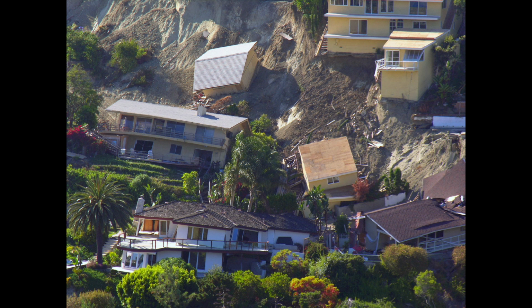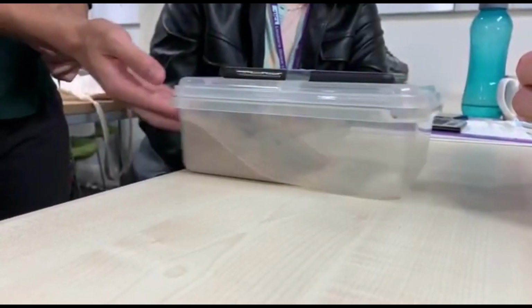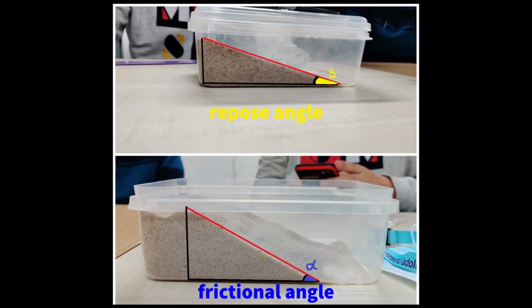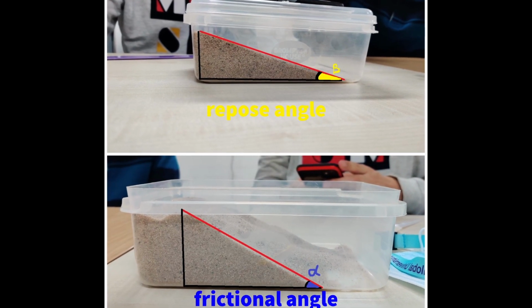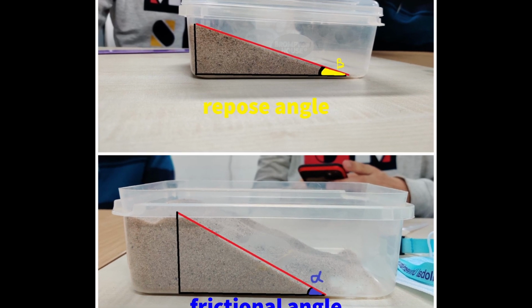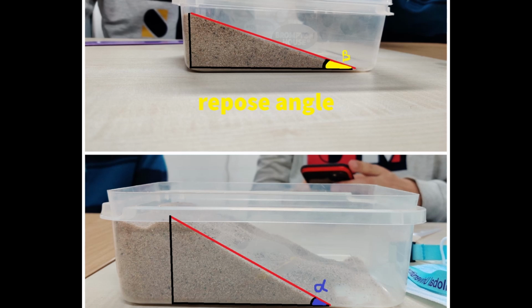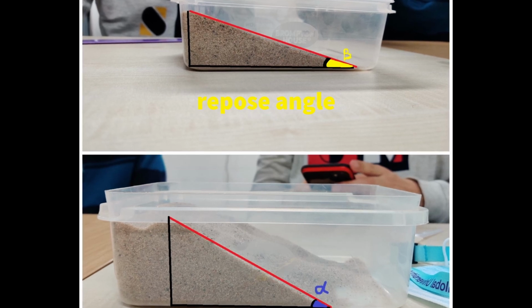Another aspect of geotechnical engineering is landslides, which is the movement of rock, earth, or debris down a sloped section of land. Landslides can also be instigated by earthquakes and can have devastating effects. We also simulated landslides as a part of the second component. We were tasked with finding the friction angle and repose angle of the granular material provided, then to determine the factor of safety compared to the 2017 Puebla City earthquake's peak ground acceleration.